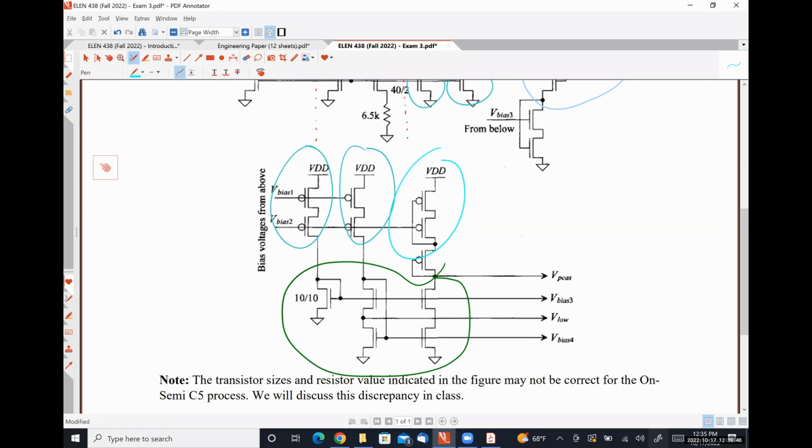So this is going to be a gnarly thing to figure out how to lay out, because all of this is happening between a common power supply rail and a common ground rail. And we have 8 different voltages that we need to make sure are correct, which means we can't accidentally cross any metal layers or we short everything out and it doesn't work right. So that's our goal for the remainder of the week after today's class meeting, is to be working on this.